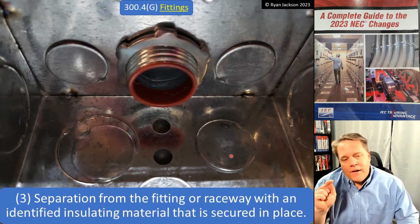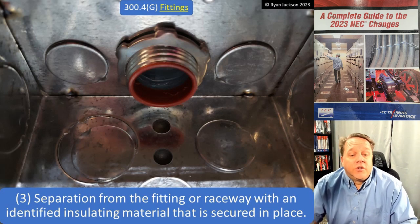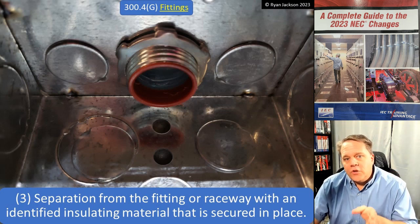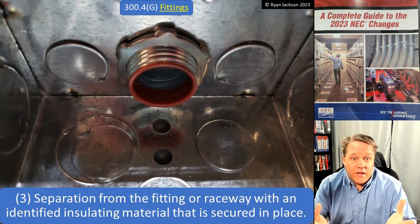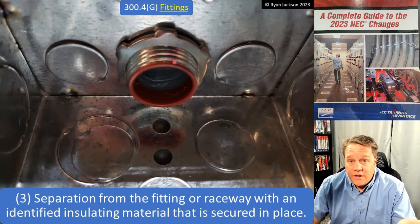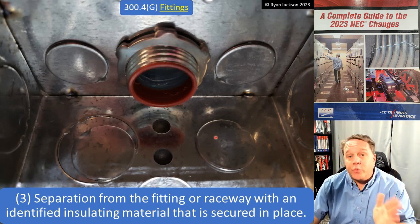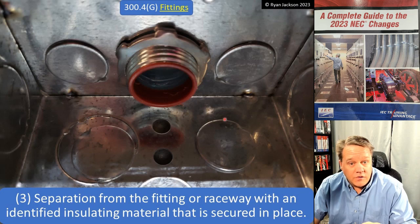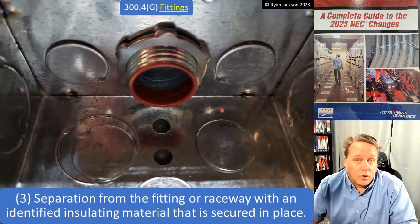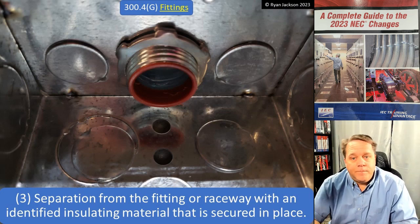Option 3. Separation from the fitting or raceway with an identified insulating material that's secured in place. All right, so usually when you see this type of product, it comes as a fitting like this and the insulating material is already installed. I'm led to believe, don't quote me on this, but I'm pretty certain that you can buy this as an aftermarket component and you can put it into your fitting. And if that's the case, well then cool, that would meet item number 3.